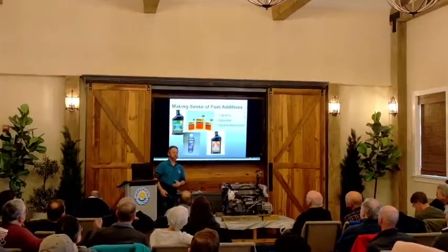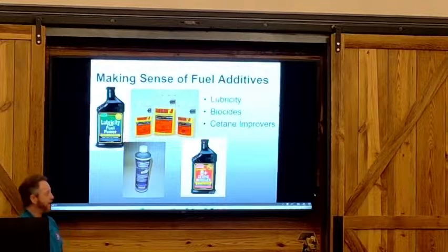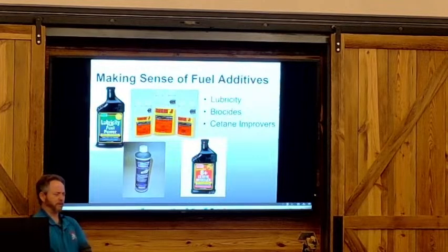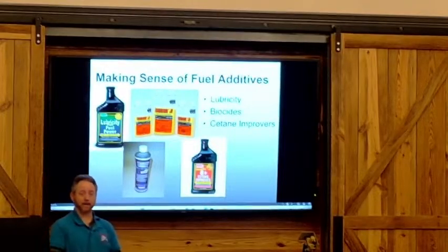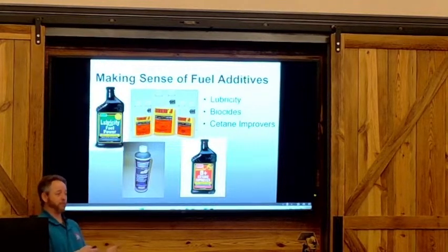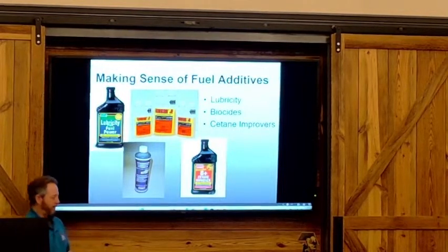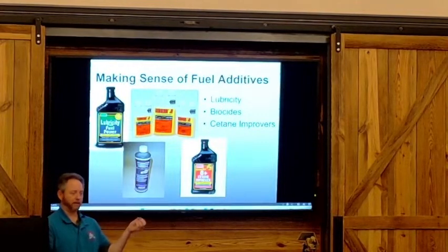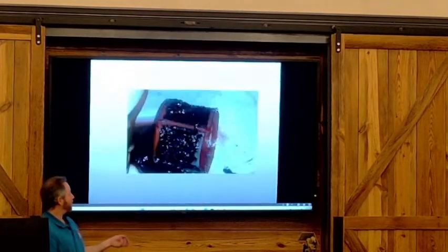All right, so there's only 3 products I would recommend putting in your fuel, and I only recommend putting it in the fuel if you have to. So lubricity products, because diesel fuel has sulfur in it. Sulfur is a pollutant, so they're slowly removing it out of our fuel, which is causing issues in our fuel systems. So if you're running low sulfur or ultra low sulfur, the sulfur in the fuel was helping protect our rubber components in the fuel system, such as if we had a rubber diaphragm.